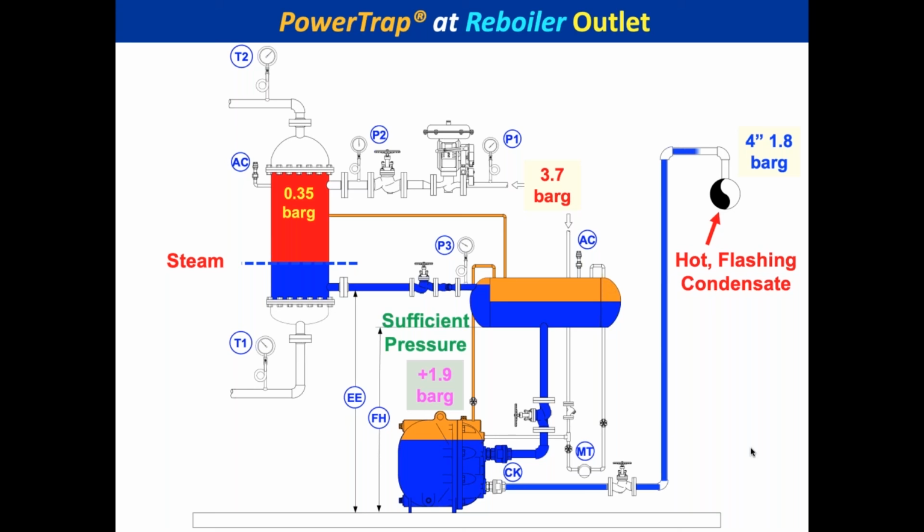And there you go. Now, depending on what the temperature of the condensate is, notice they're happy now, right? This is a happy face. But it depends on the temperature of the condensate coming into that line. If the temperature coming out of that is still going to be close to like 94C or something like that, or maybe close to 100C, I might put the entry point here into the side rather than the top.